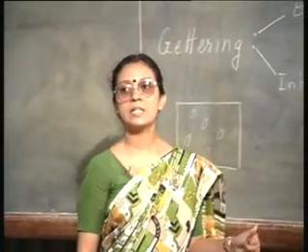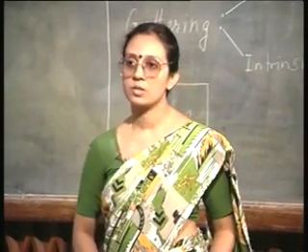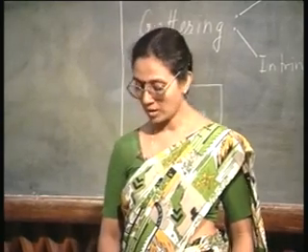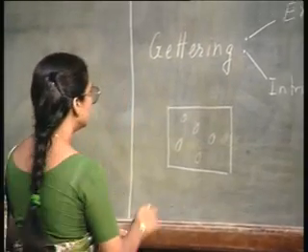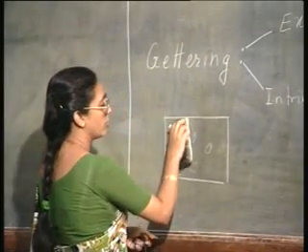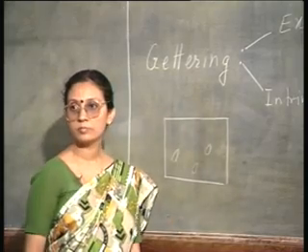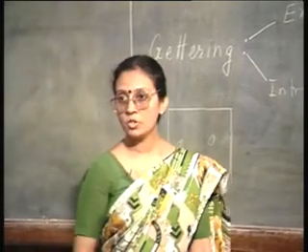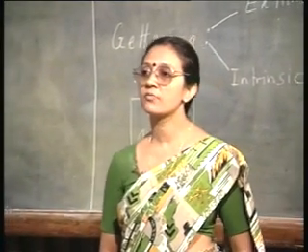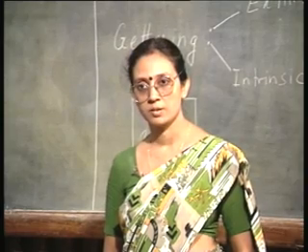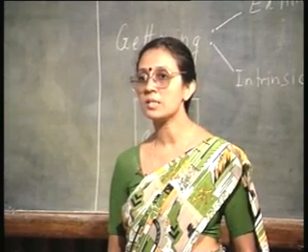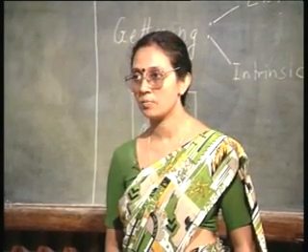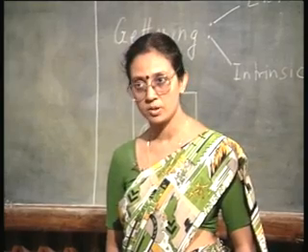Now, I heat this wafer at 1000 degrees centigrade or above in an inert ambient. What will happen? The oxygen from near the surface will evaporate out. So, the active region is free of these oxygen precipitates, but I still have oxygen precipitates deeper in the bulk, which can be used as gettering centers, which can be used as sinks for metallic impurities.